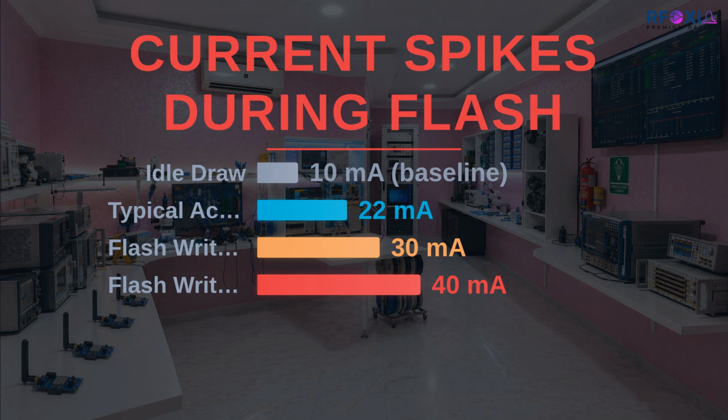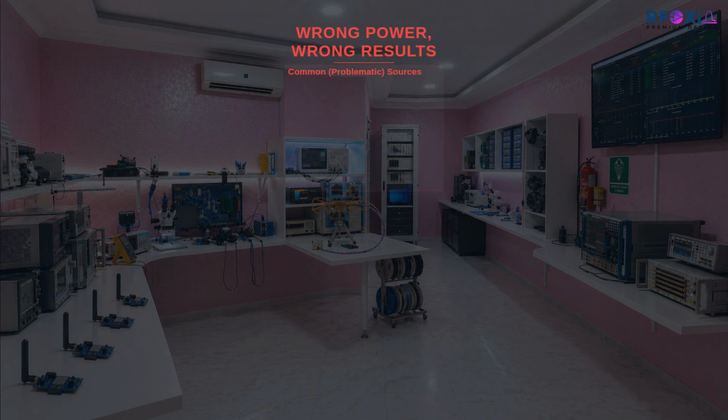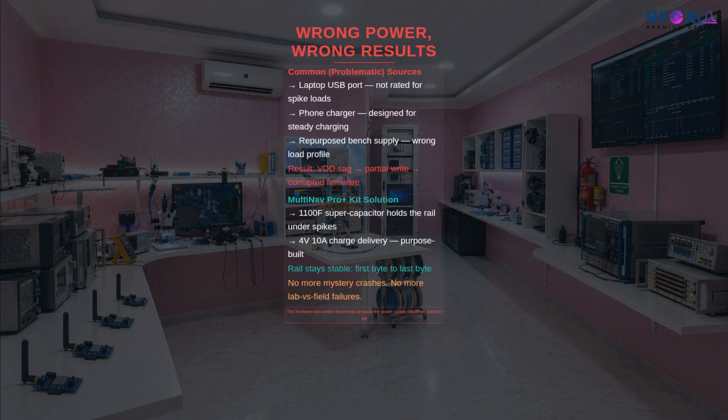Now consider where most developers get their power. A laptop USB port, a phone charger, a bench supply that was designed for audio equipment and repurposed because it was available. These sources were not designed for this load profile. When the current demand spikes, the voltage drops, the microcontroller's VDD rail sags. If it sags far enough, even briefly, the flash write circuitry may complete a partial write and then receive corrupted data, or the core may experience a brownout reset mid-operation.